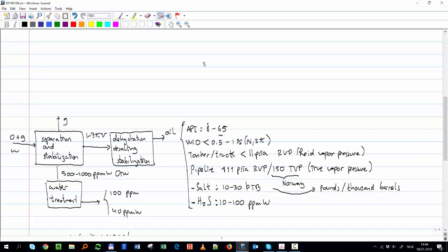What was the next step for gas after I separate? Remember, for the exam, you have to know it. You know, I wake you up in the middle of the night, you have to answer. Hydration, right? Okay. Why? We don't want any water coming out of solution from the gas.